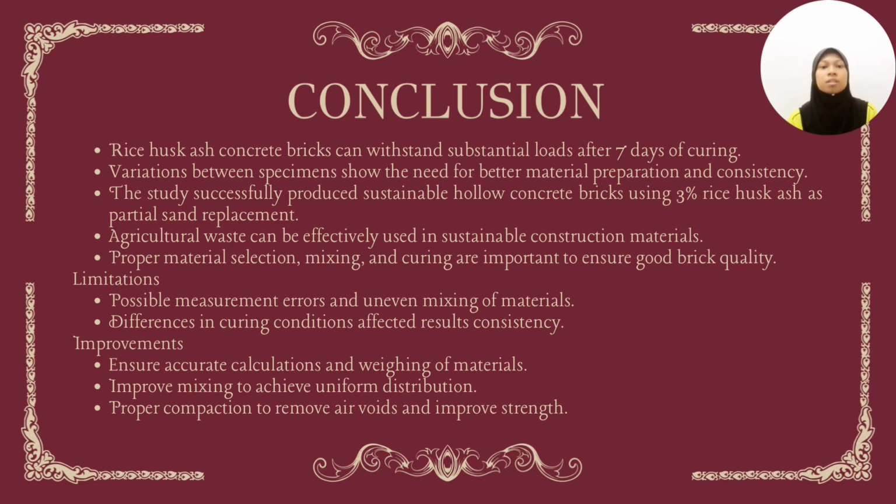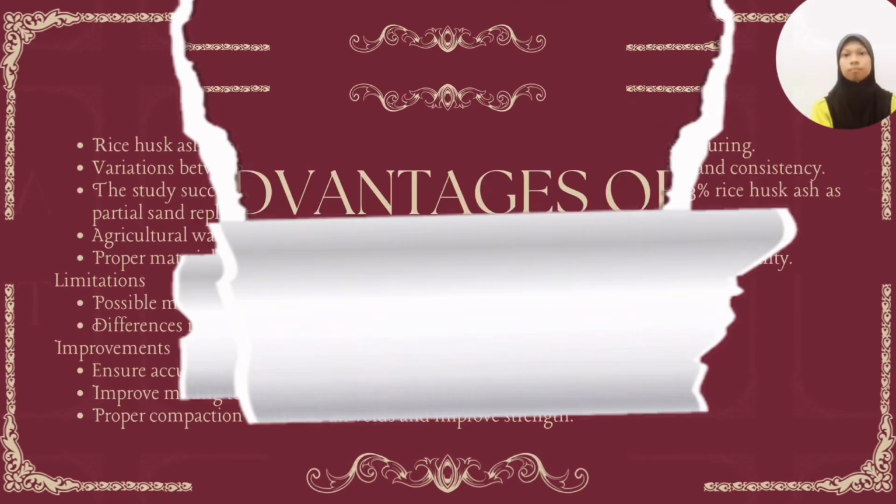For limitations, possible measurement error, uneven mixing of material, and differences in curing condition affect result consistency. To improve that, we have to ensure accurate calculation and weighing of material, improve mixing to achieve uniform distribution, and proper compaction to remove air voids and improve strength.